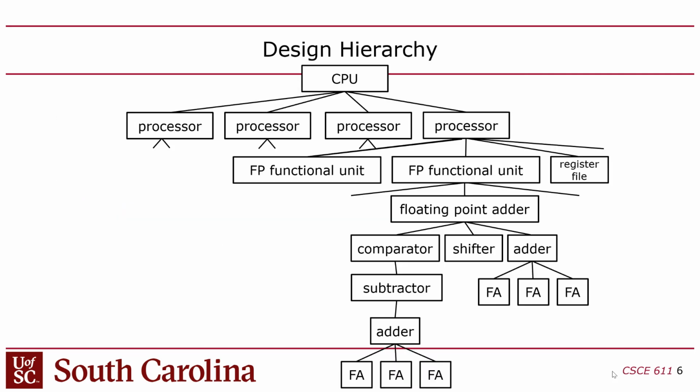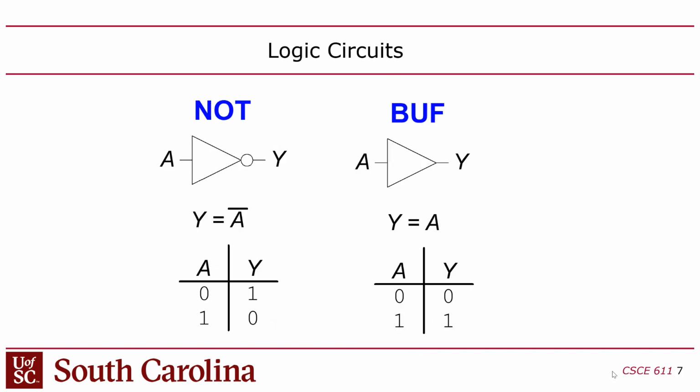We talked about abstraction, hierarchy, and regularity. And this is important for you to understand because this is essentially how Verilog works, and HDLs, it's all based on hierarchies of modules. The idea is that you create modules that hopefully can be reused as much as possible, and then you create increasingly complex designs by creating this hierarchy of modules that when you collapse the hierarchy, when you flatten the hierarchy, it's a huge digital design, but when you look at an individual file, for instance, it may not be that complicated, right? You may just have a few modules instantiated.